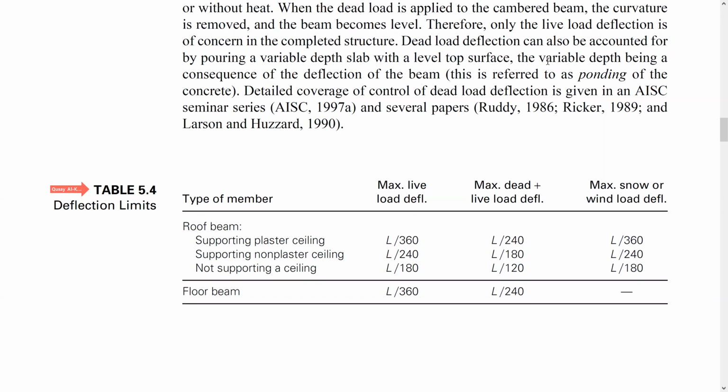Okay. So as I mentioned to you guys, deflection is a serviceability limit state, meaning it is not a strength limit state. The strength limit state for the beam relates to shear and bending moment capacity. But deflection is a serviceability limit state, so we should compute the deflection under service loads. Meaning the loads should not be factored; they should be unfactored service loads, as they are.